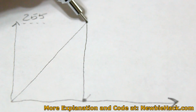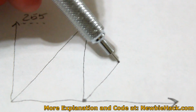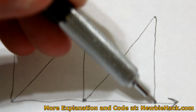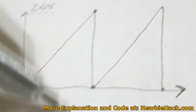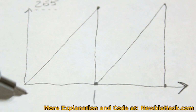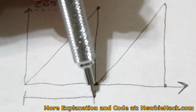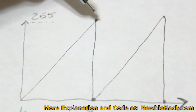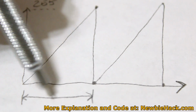And this is called the overflow with the 8-bit timer. It goes back down to 0, and it counts up, and then it goes back down to 0. And if we wanted to use the 8-bit timer, this would essentially become our period. In the 8-bit timer, it only has a few variations because it always overflows at 255. We can create prescalers to slow this down.